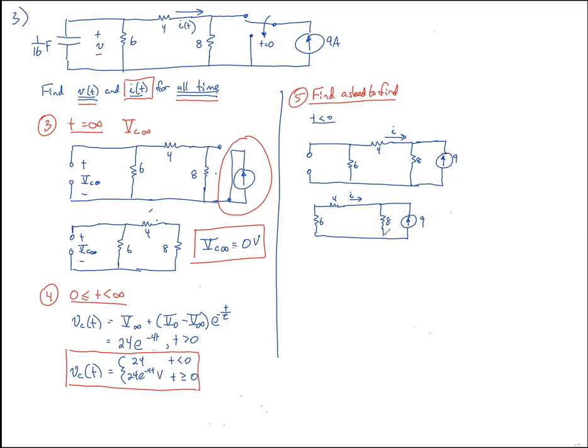And when I look at this circuit, I can see that these 4 and these 6 are in series. So I can simplify it down to 10, 8, 9. And again, look how careful I've got to be about where I draw this I. If I make a mistake and draw the I this way, it's wrong, because this I comes before the 8. I have to say it's in this direction. And I haven't destroyed anything by combining these guys, because these are outside the I.